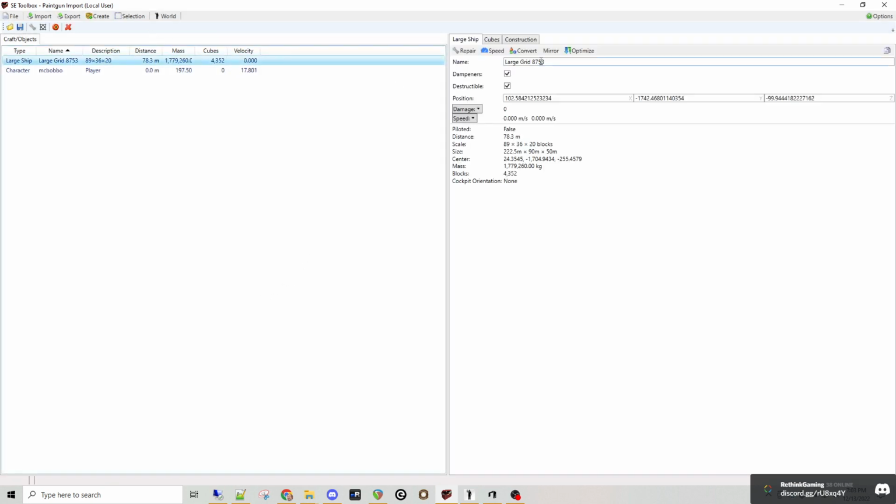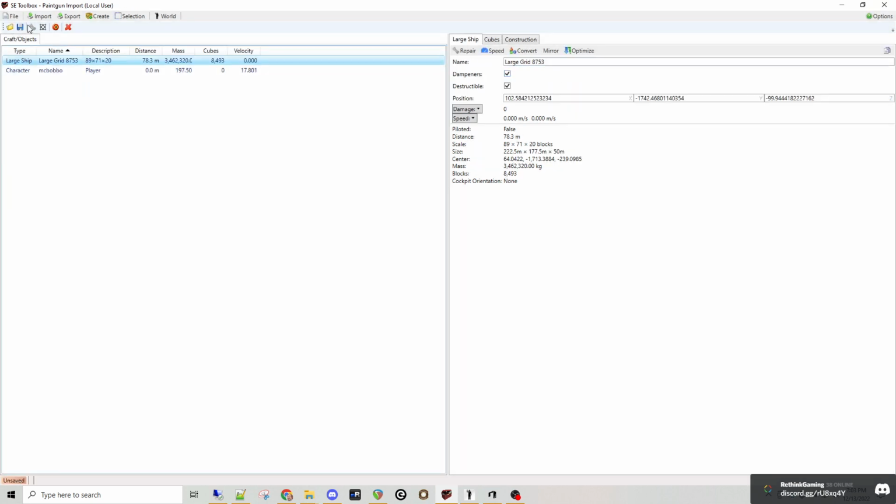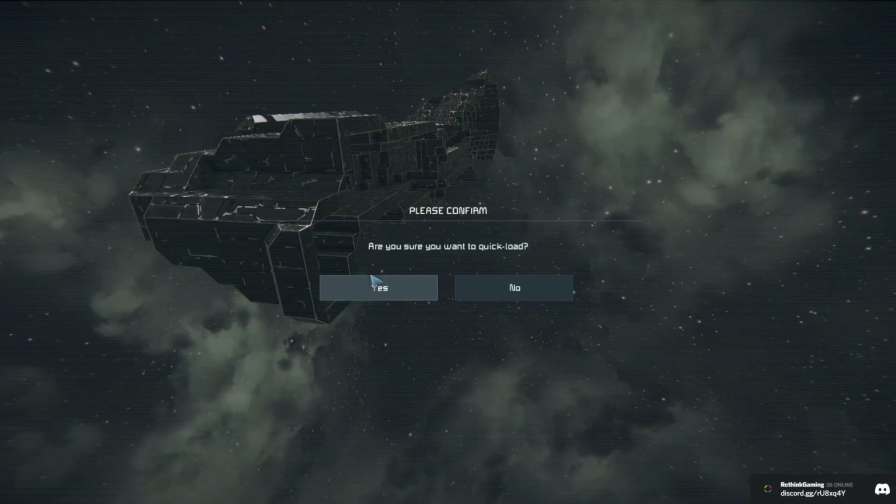And then in SE Toolbox, I can do mirror using predefined symmetry planes. Now, if you haven't predefined them, you can do the find largest surface thing, but it's just better to predefine the plane. You're going to want it when you're doing your creative build later anyway, so you get your connectors and all that sort of stuff in symmetrical places. So we did that and we saved.